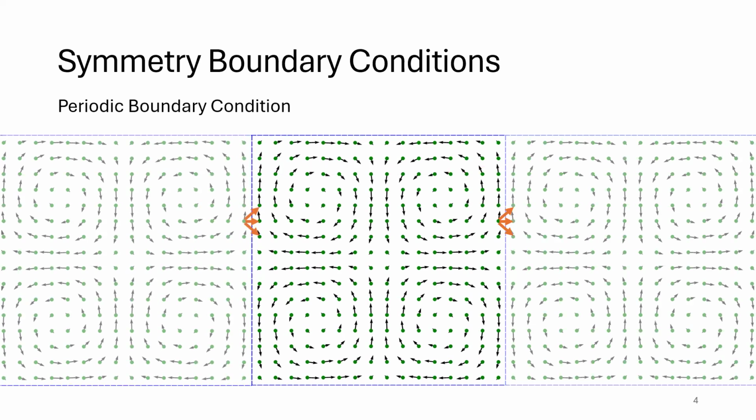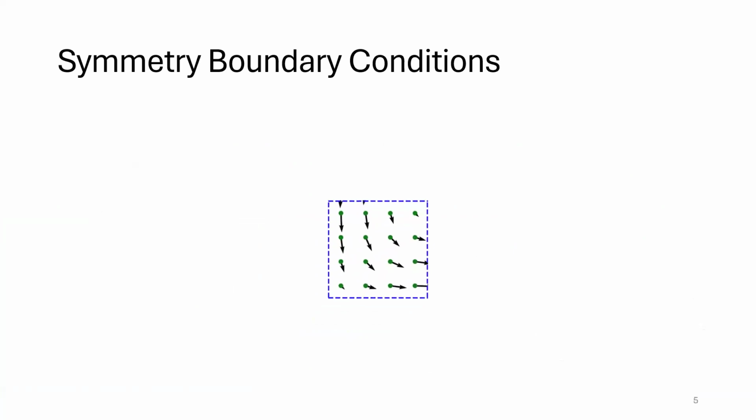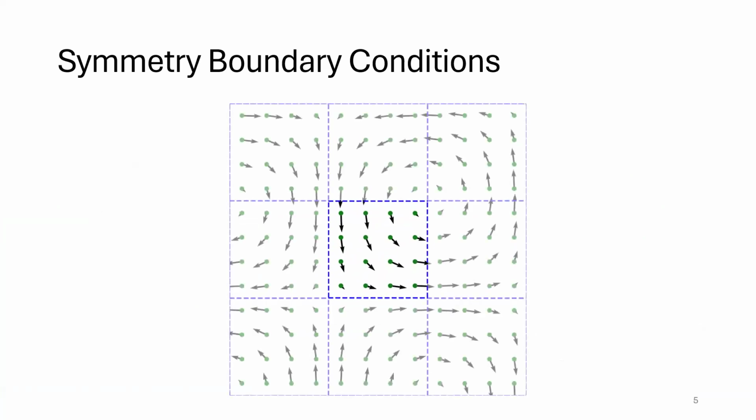And it is, and that's important, standardly implemented in the Lattice-Boltzmann code I'm using at the university where I do the research. So right now, we're just going to take this little part, and the surroundings are going to look like this. So if we find an outlet right here, we are going to find it as an inlet right over here. It is shifted and rotated. So the problem is this node is non-existent. So what can we do? In every time step, we are going to put this population, which would realistically appear right here, on the opposite side where the node is existing.